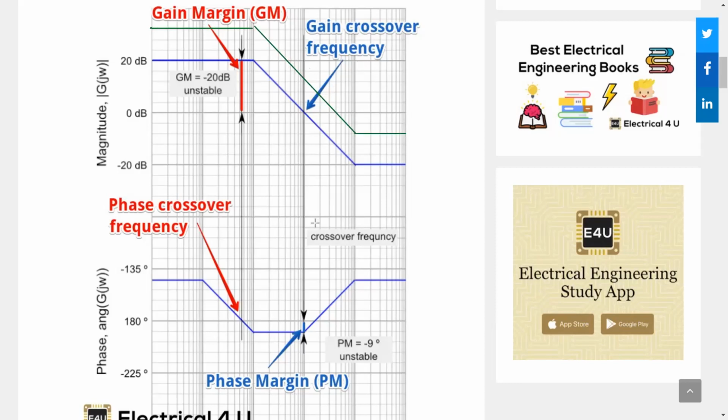Now this danger point again. Danger point, by the way, is just me using simple words. That's not how, like gain crossover, you see phase crossover frequency, that's what they call it. But I think I can allow myself one made up term. This danger point goes away, but we have a new one here.